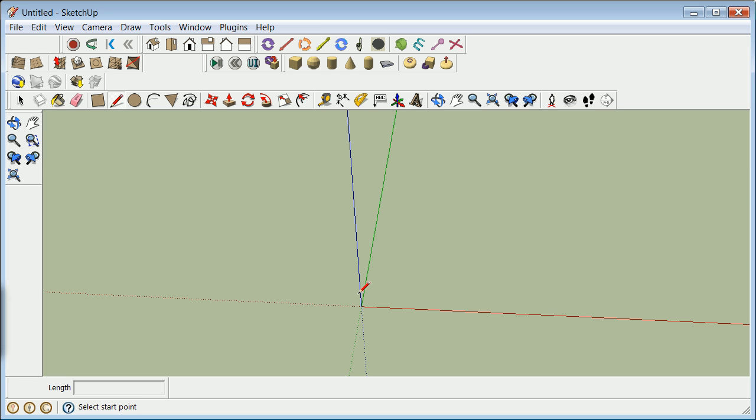But when you bring in terrain from Google Earth, you have to look at the layers and realize that there's one layer that is a snapshot, another one that is a photo rendered tin, more or less. And so that is something that you can then deal with to do things called drapes and stamps, to more or less project information off of a 2D design plane and have it pick up the 3D information of, for the most part, an existing tin or existing digital terrain model. So we're going to go through the tools.